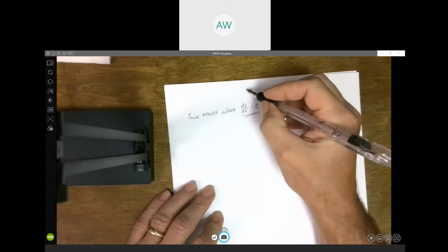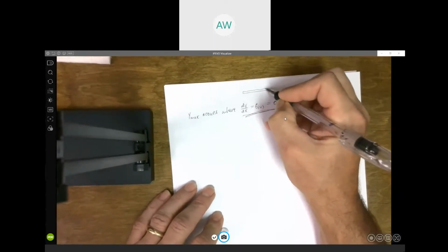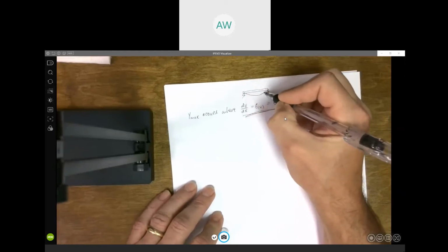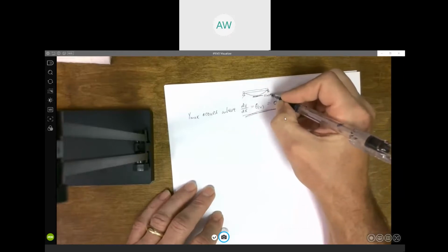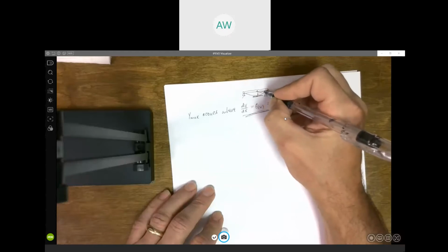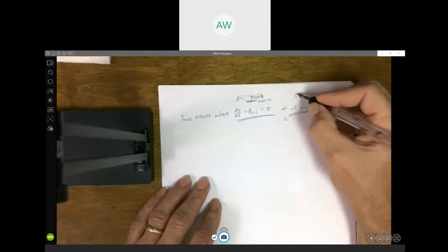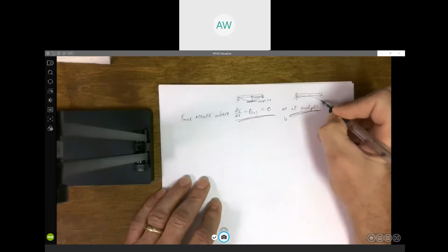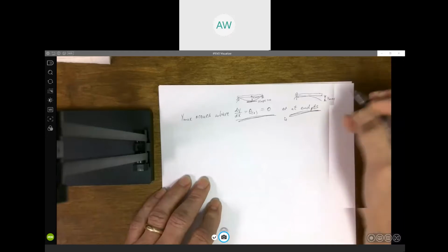This would occur, like the one we just worked, if you've got a simply supported beam. It's going to deform. That's where you get the slope equals 0. That's where you get y max. The endpoints would be like if you had a cantilever beam. Say this thing bends down like this, like the one we worked yesterday. That's where you would get y max, at the end.